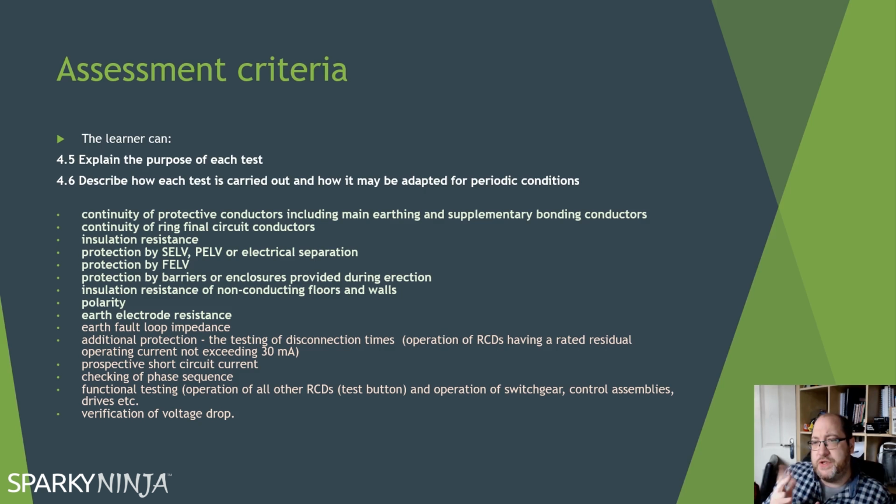Polarity, there are two types of polarity. There's obviously the dead polarity and the energized polarity. The dead polarity mostly will be confirmed on the initial verification with the continuity of protective conductor test, the R1 plus R2, but you'll need to verify that polarity is there for 3-phase, for triple pole switches as well. If you're doing just the R2 test, or you're working on a periodic and you're just doing the R2 around, then you need to say, how are you verifying polarity? Will you consider your Zs test as a verification of polarity? So, you need to make sure you verify polarity one way or the other.